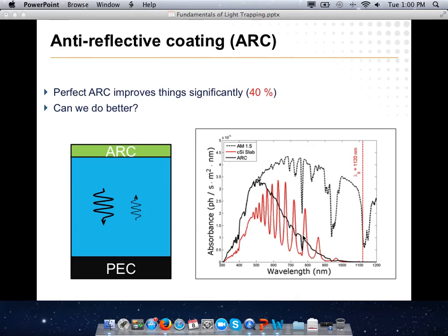You notice all those little resonances went away, but I also collected a lot more area under this curve, and we suddenly find we're getting about 40% of the total energy. So it's a little better, but it's still kind of terrible. Over half my photons are still just kind of entering and leaving. And you also especially notice it's really bad as I get out here towards the longer wavelengths. In fact, you get up very close to the band gap, and almost nothing is really being absorbed. So I'd really like to do better than that.